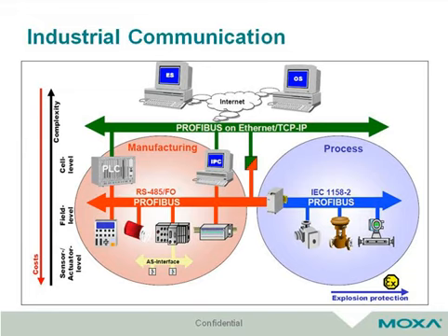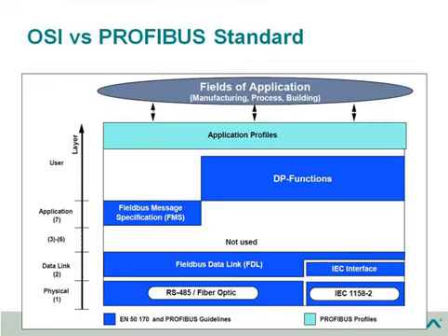The information flow requires large data packets and a large number of powerful communication functions. And smooth integration into company-wide communication systems such as intranet and internet via TCP/IP and Ethernet are important requirements. After learning about the industrial communication and knowing that it uses the PROFIBUS protocol because of efficiency and real-time communication, let's learn more about the PROFIBUS standard based on the OSI model.